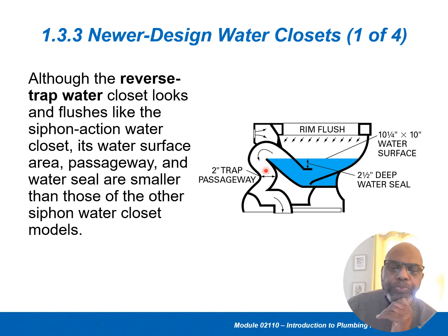And so when the water levels start to increase and go to a certain point, it actually causes siphoning action to overcome that height, and it will drain. But it will stop right there to keep any gas or water from coming back in. So if you overfill it sometimes, and too much water goes through, it can siphon all the water out of it, and it would be basically empty, especially if it's not feeding more water back into it.